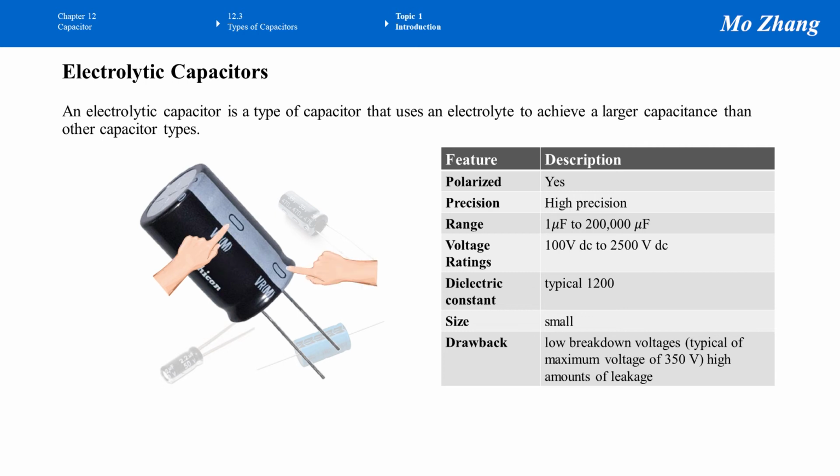And if you look even closer, it has this sign. It is a negative sign, which means the leg attached to this ribbon, or the leg this ribbon is pointing at, connects to the lower voltage in the circuit. This implies this kind of capacitor has polarity. If the capacitor is connected incorrectly, there's a chance we can blow up this capacitor. So the key is that orientation is very important, since the electrolytic capacitor has polarity.